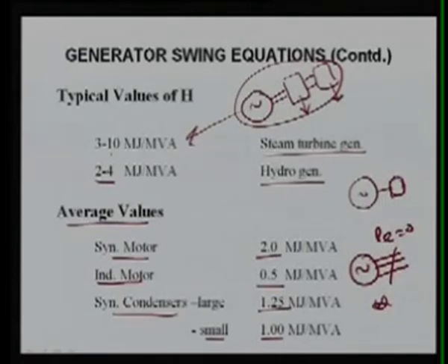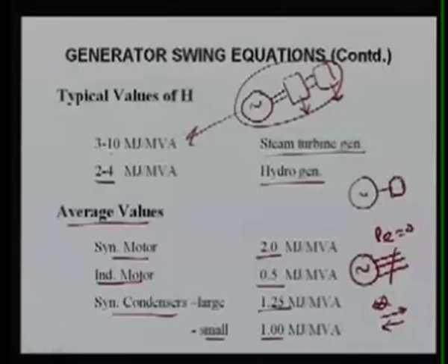So you can either generate or absorb reactive power by this synchronous alternator. We know that by changing the excitation system, we can generate or we can absorb the reactive power. So it is acting as some variable capacitor along with the inductor. See, in one zone it is giving, in another it is also absorbing. So it can do that, and we are not taking any real power load, then it is called a synchronous condenser.